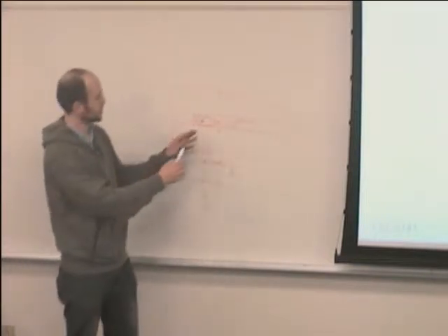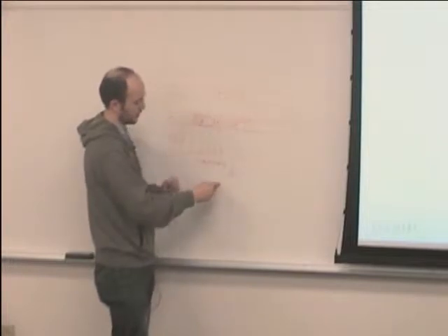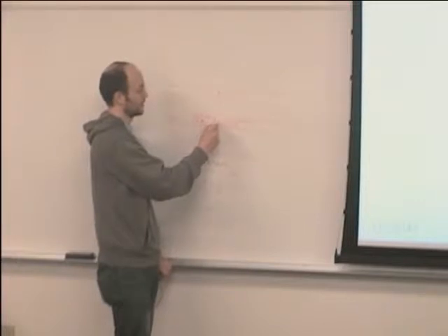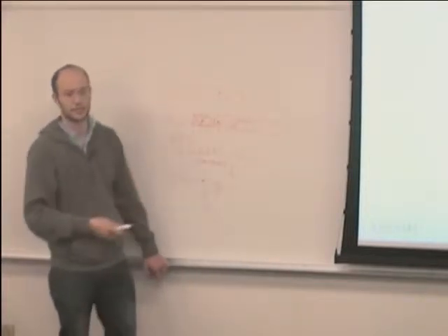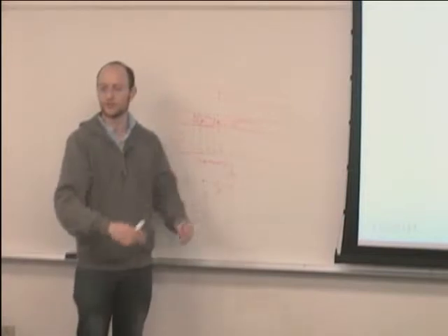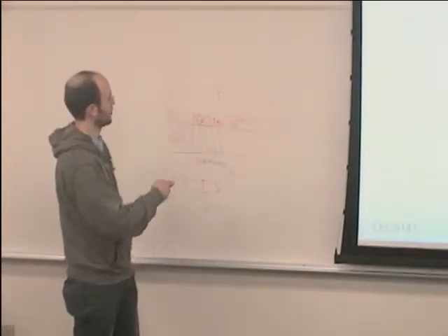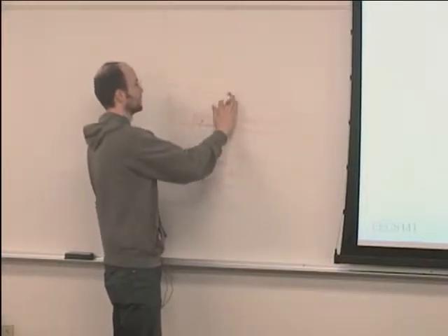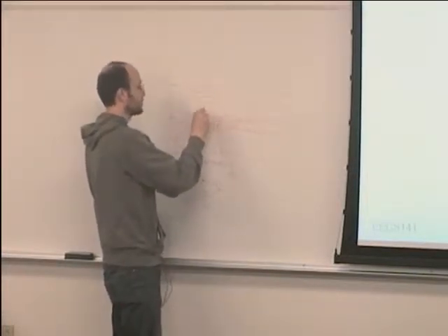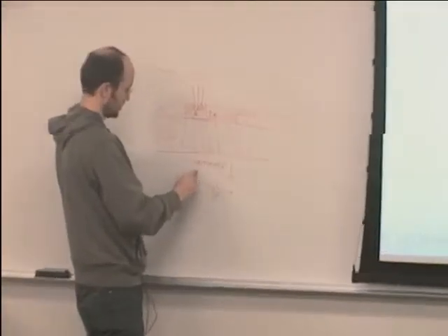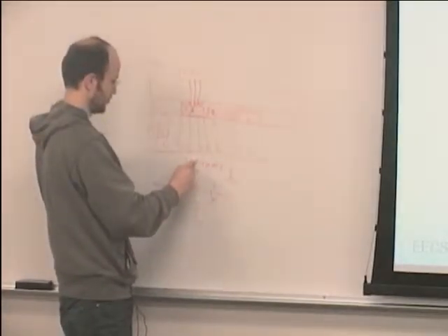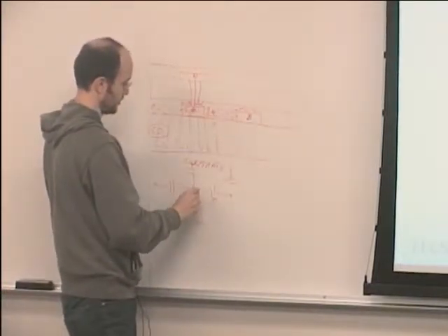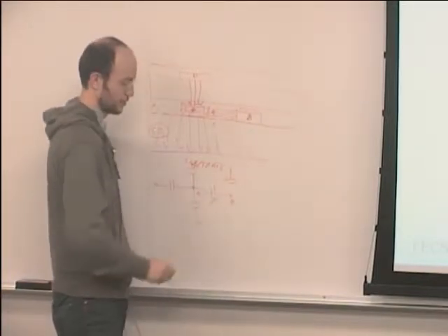And so obviously the closer these wires are, the higher this capacitance is. And then also the thicker these wires are, the higher the capacitance is, because it's just like a parallel plate to first order, right? So you should have already seen all these. And then, similarly, if you have a wire on top, then there will be fields going like this, right? And so there will also be a capacitance to call this D, A, B. So if this is A, this will be D, and this will be B, right?